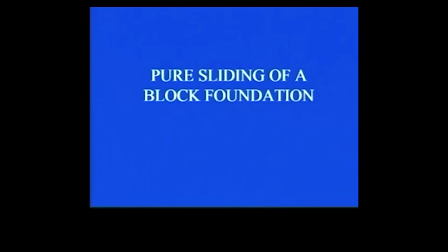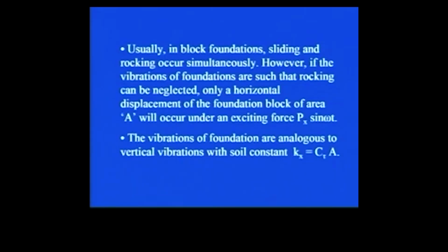So, in that sequence let us start how the block foundation is analyzed when it is subjected to pure sliding. Usually in block foundation, sliding and rocking occur simultaneously. However, if vibrations of foundations are such that rocking can be neglected, only a horizontal displacement of the foundation block of area A will occur under an exciting force Px sin omega t.